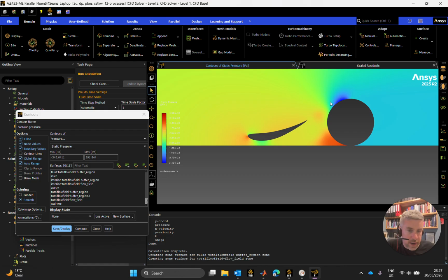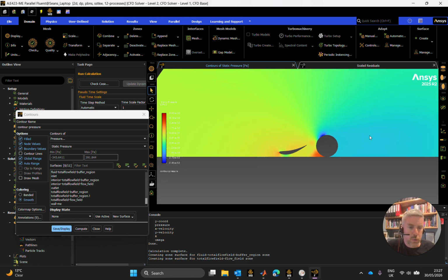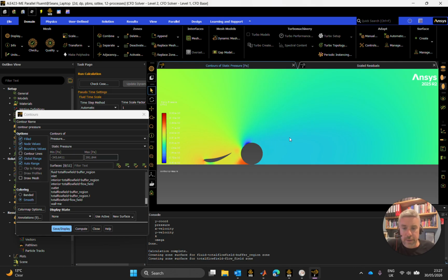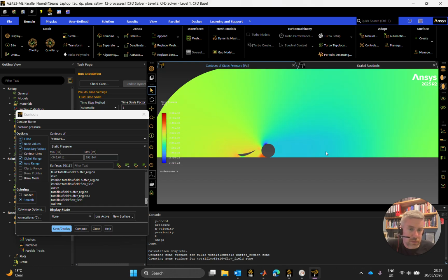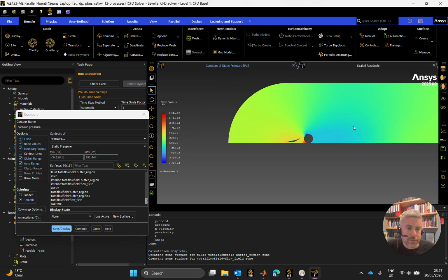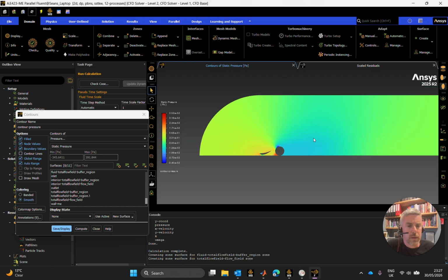So if we can maybe take air away from this, lower the energy of the air here, we might allow the higher pressure air to take more of a hold over the top of this wheel. So these are certain wee things that we could maybe look at and alter the profile and the chords and the angles of attack of this front wing to try to deal with. And again, we're back into a big low pressure region here, or in behind the wheel, which is odd as well because we have very low velocity in there too. Okay.